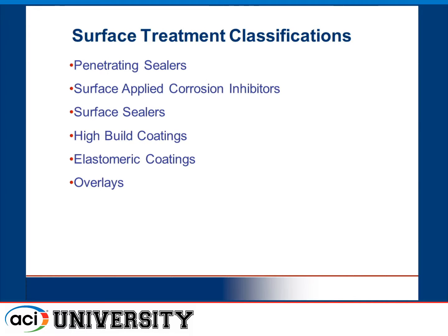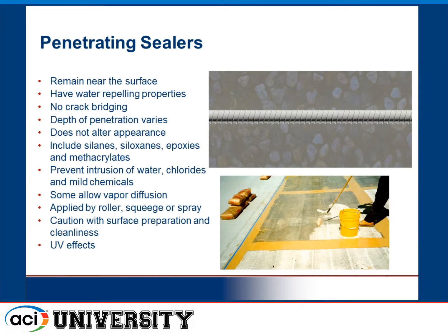Penetrating sealers, as the name implies, consist of basically applying a coating on the surface and allowing it to migrate to a certain depth, penetrating the porosity of the concrete. They remain near the surface, and some of them are water repelling. And they don't have the ability to bridge cracks, although there may be some very, very small hairline cracks.